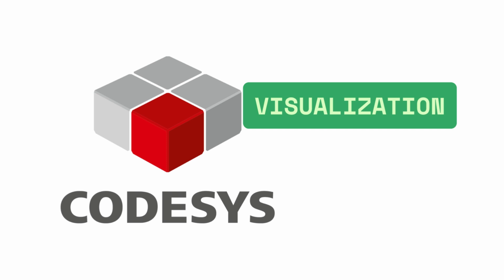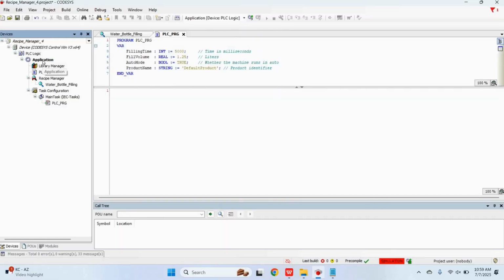Now let's talk about how to create and work with a recipe manager using visualization in CODESYS. This is especially useful when you want operators or users to interact with recipes through a touchscreen or HMI interface instead of going into the engineering interface. To begin, the first thing we need to ensure is that the recipe management library is included in our project.